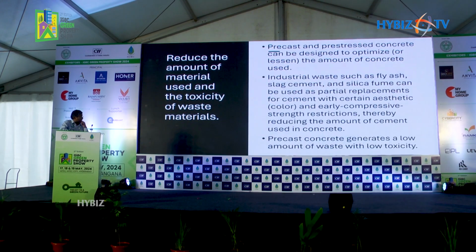Precast concrete can be designed to optimize or lessen the amount of concrete used. Suppose we are using load-bearing walls instead of framed construction for multi-story buildings, just like in monolithic construction or in precast walls, whereby the wall thickness is lesser, with no more brick masonry or plastering, thereby a lot of economy in the construction, no plastering, no painting, which is a beautiful advantage.